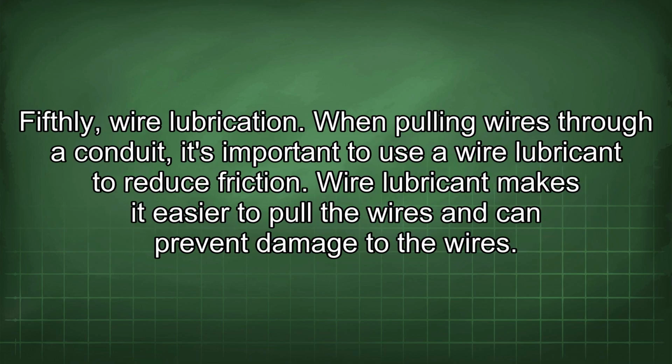Fifthly, wire lubrication. When pulling wires through a conduit, it's important to use a wire lubricant to reduce friction. Wire lubricant makes it easier to pull the wires and can prevent damage to the wires.